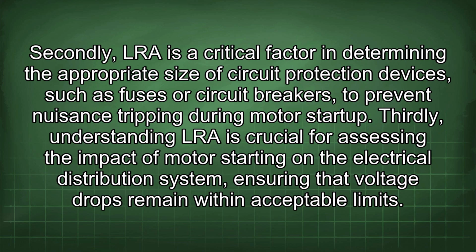Secondly, LRA is a critical factor in determining the appropriate size of circuit protection devices, such as fuses or circuit breakers, to prevent nuisance tripping during motor startup. Thirdly, understanding LRA is crucial for assessing the impact of motor starting on the electrical distribution system, ensuring that voltage drops remain within acceptable limits.